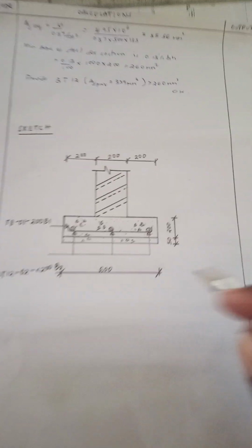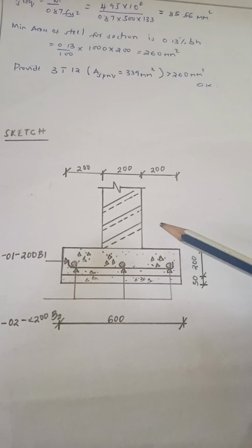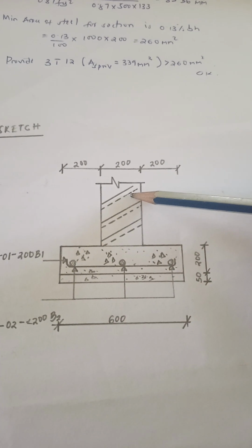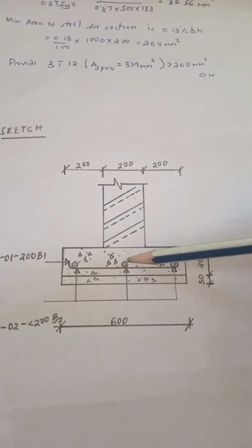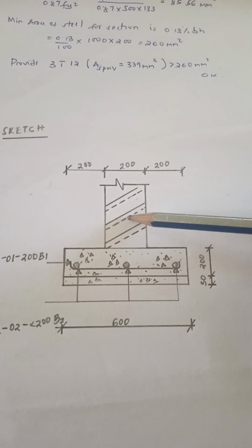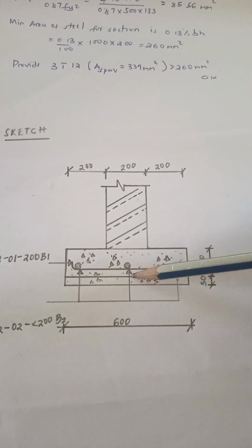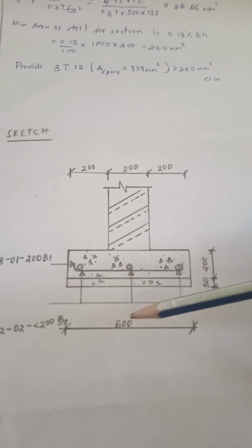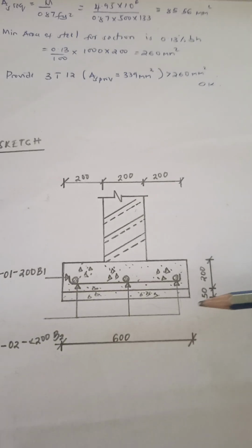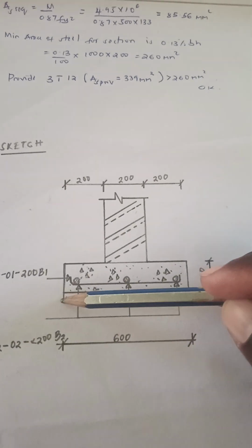Remember the design for cantilever moment comes about because the load bearing wall sits at the middle of the footing, therefore creating a point load to the footing, and the footing itself also experiences a pressure from the soil through the entire width.